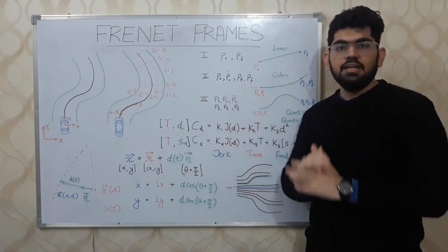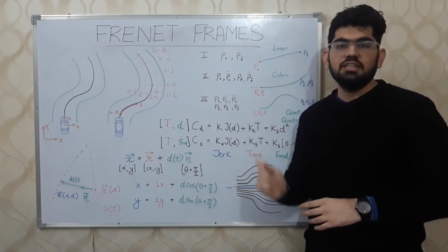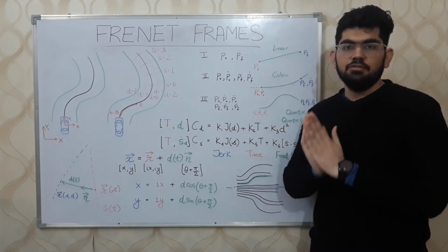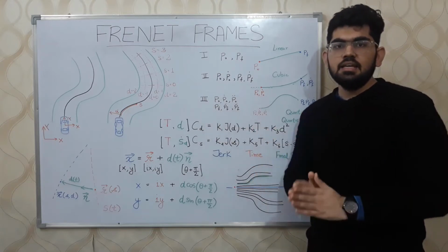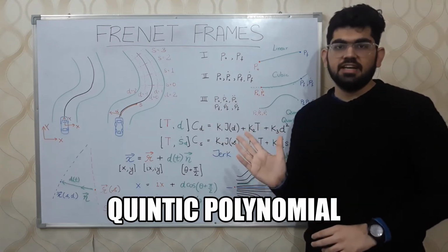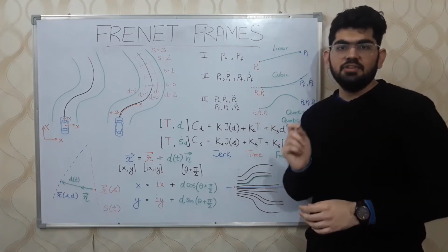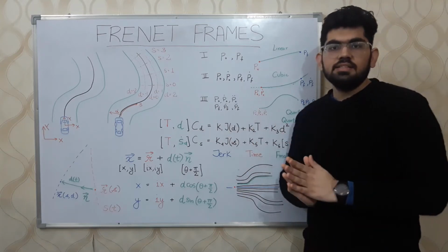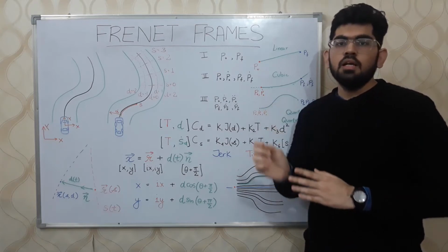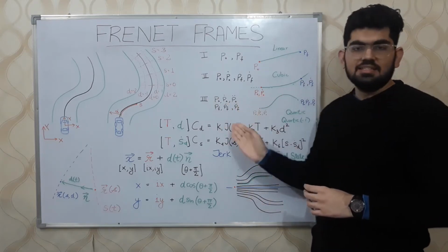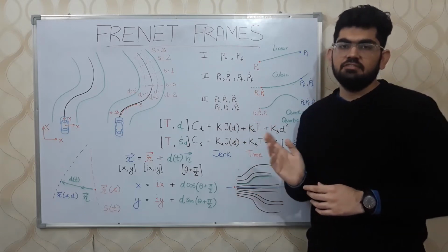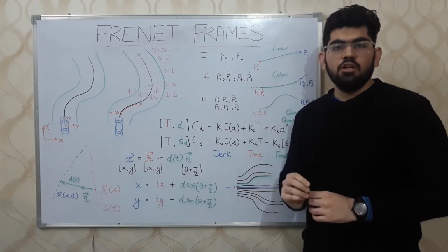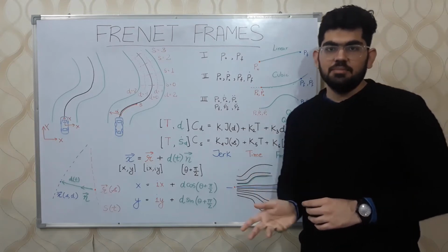In the third case, in addition to the speed and position, we are also given the accelerations. In this case, the smallest polynomial that can be fit between the initial and final states is a quintic polynomial, a polynomial of degree 5. A 5-degree polynomial has 6 variables. These 6 variables can be satisfied by these 6 constraints. Now consider another case where we slightly reduce the problem and remove one constraint from these 6 constraints. Hence, we now have 5 constraints that we need to follow. For these 5 constraints, we can fit a quartic polynomial, a polynomial of degree 4, which has 5 variables.